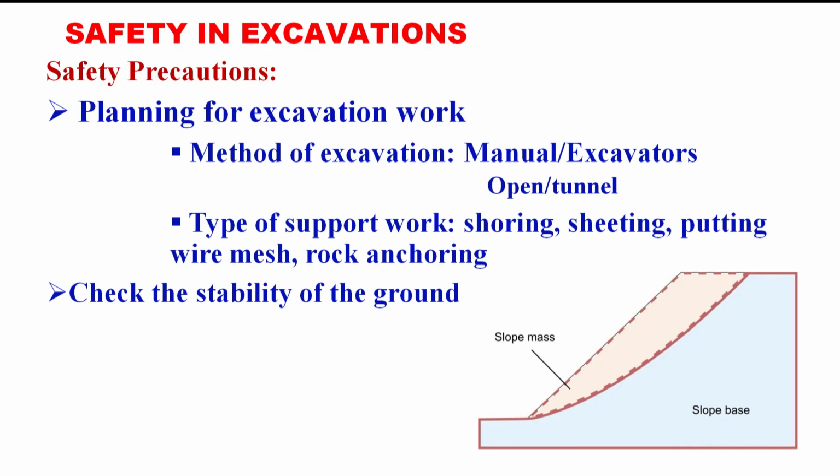Then we have to think about the type of support work that will be needed when we are doing the excavation. In open excavation, when we are digging trenches, after a certain depth soil cannot stand vertical by its own. It needs support, otherwise it will cave in. The soil from both sides of the trench will cave in, hindering the work and possibly injuring the workers.